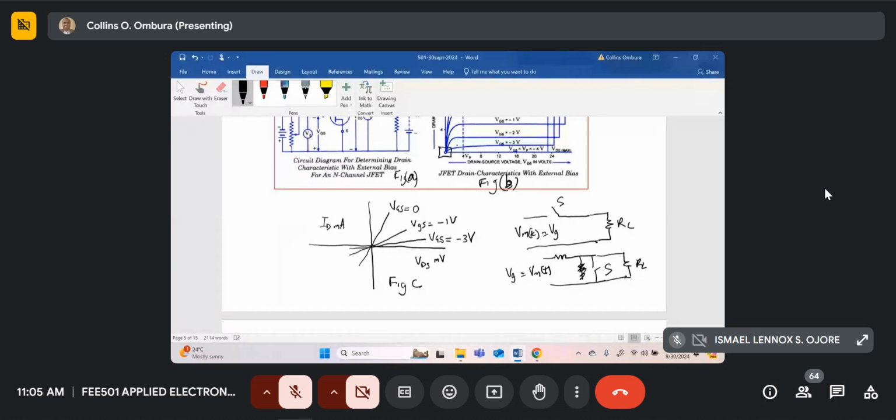So when you're dealing with choppers, this is the region we're interested in. We're not interested in the large signal characteristics of the FET. So our switch is going to be operated in this region, where VDS is in millivolts, less than 50 millivolts. IDS will be very small, milliamps or hundreds of microamperes.